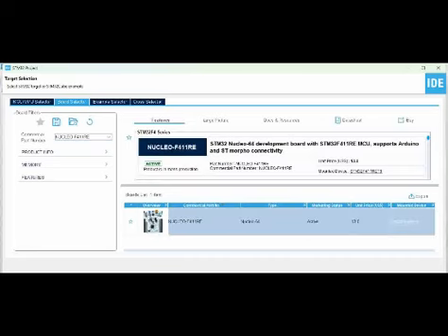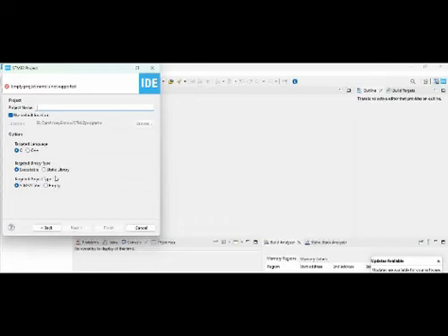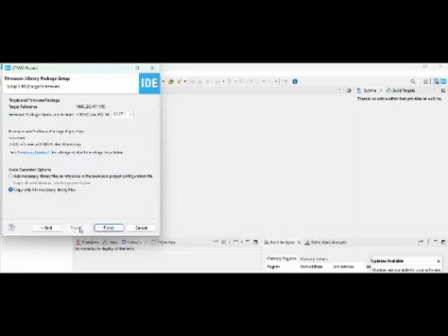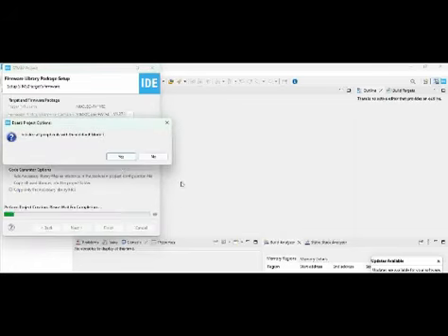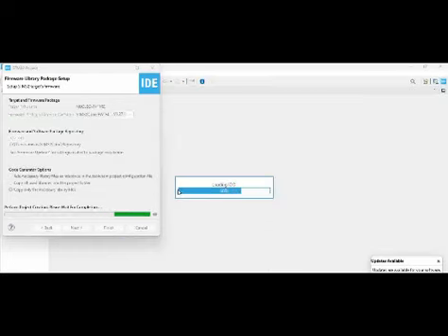Click on this, click next. We want Blinky LED code, right? So let us type that and then click finish. Don't make any other changes. So it is asking initialize all peripherals with the default mode. Yes, let us initialize the peripherals with their default mode.